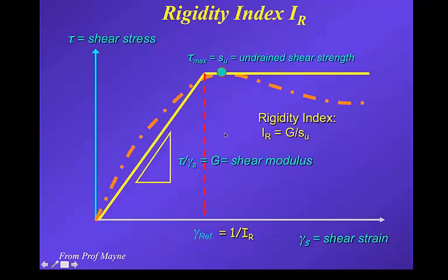And secondly, the soils are going from that recompression mode to the normally consolidated mode, or to the stress history that exists in the ground. So if the soil is over-consolidated in the ground, in the initial stages it's more over-consolidated, and then slowly gets to the spot where it's at the stress history that it is in the ground. So T50 is nominally that spot where it matches the in situ conditions. Of course, not perfect because the theory's not perfect.